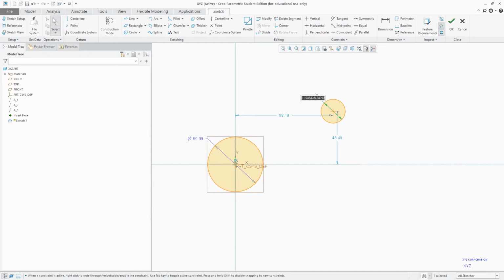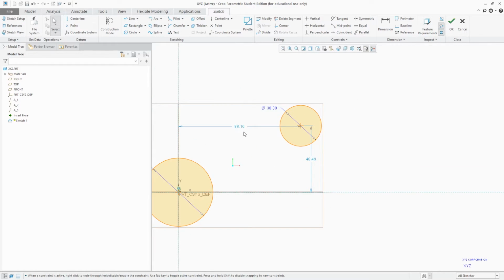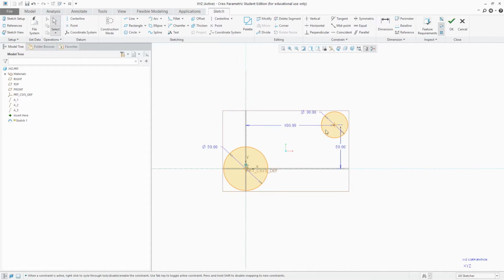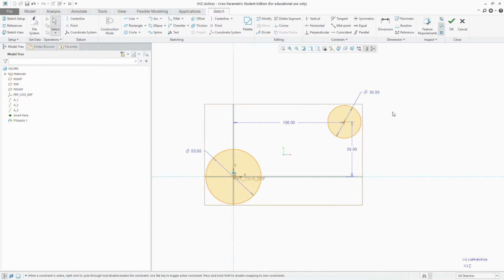But here we need to give this thing a dimension. Also, you need to locate this thing in 3D space. So Creo automatically has created two X and Y values. Now you need to provide where you actually want to place it. For example, 100 of X and 50 of Y. Now please keep in mind, whenever you change the value of a dimension, it turns royal blue from sky blue, because this shows that this dimension is now strong.